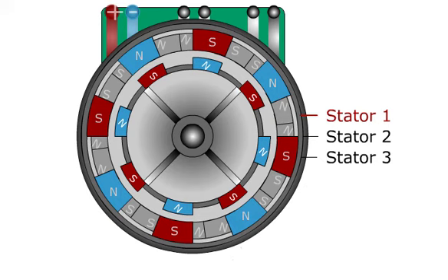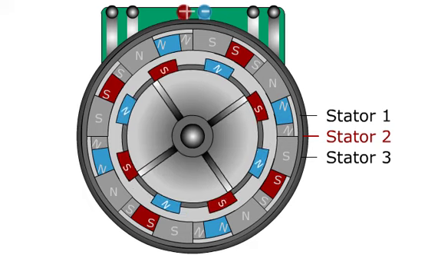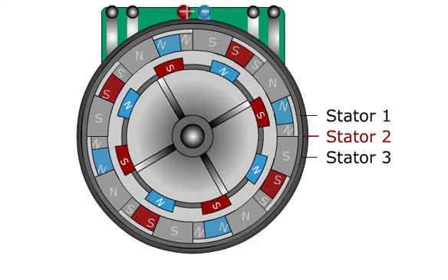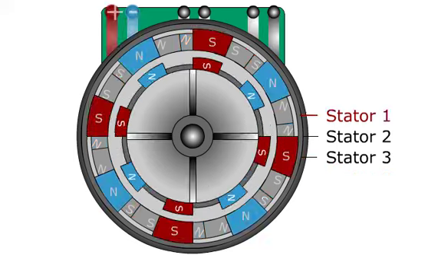If stator part 2 is now energized and thus magnetized, the rotor turns clockwise by exactly 2/3 of pole width W. This rotates the motor. This procedure is continued by energizing stator part 3 and the rotor turns by the same amount. This ensures a continuous rotation of the stepper motor.